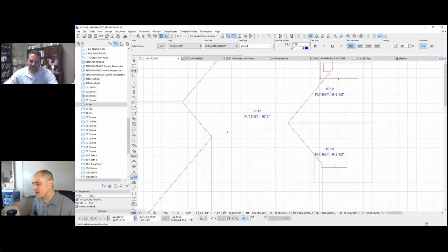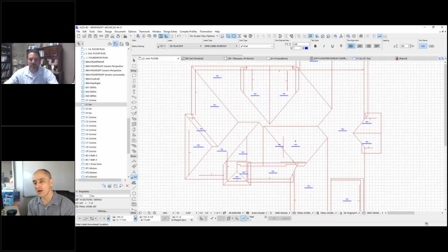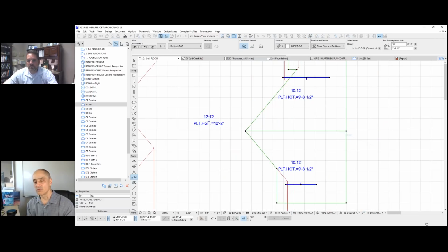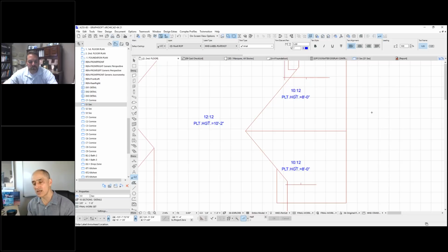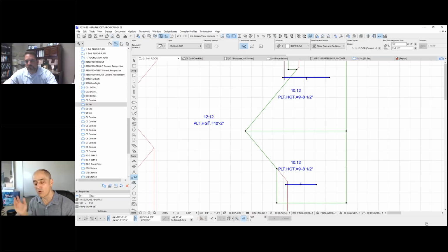How did that affect the fascia height? Scott asked. So the simple way that you draw a roof in ArchiCAD is you have a uniform volume that includes the shingles or top cladding, the plywood, whatever space you have for insulation, and if it was a slanted ceiling, you might include that.